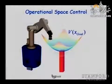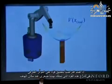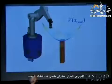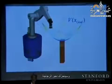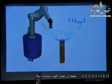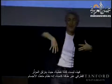So if you virtually apply a force at the end effector that is the gradient of a potential which has its minimum at the goal position, essentially this end effector is going to fall in this potential energy and move towards the bottom, right? Well, you don't know exactly how it's going to move, because this is not a point mass you're dropping in a potential energy, it's a multi-body system.